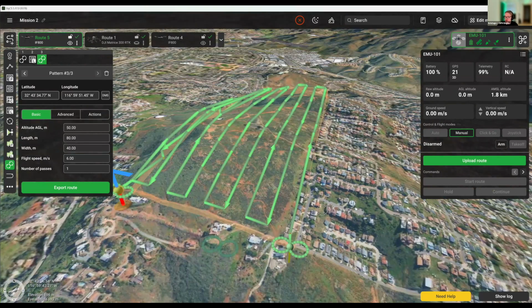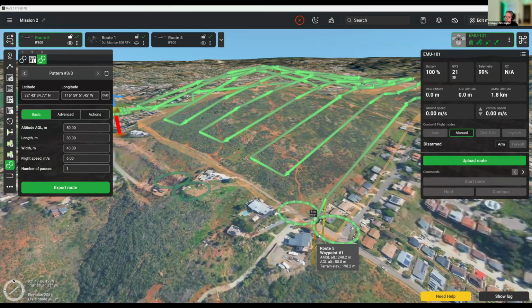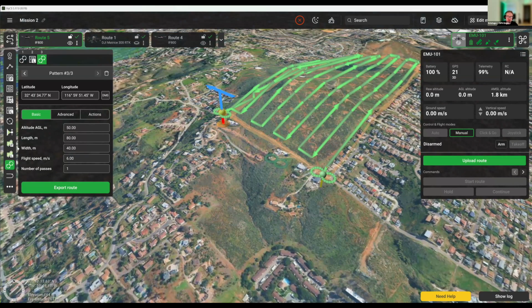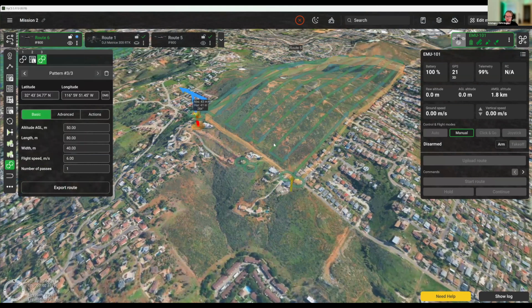And then also, if we're using a YellowScan LiDAR, then instead of doing the figure eight calibration, it's recommended to do the U-shape / J-hook calibration pattern. So now to do that, I'll also show you one interesting thing here: I can just duplicate this whole route.